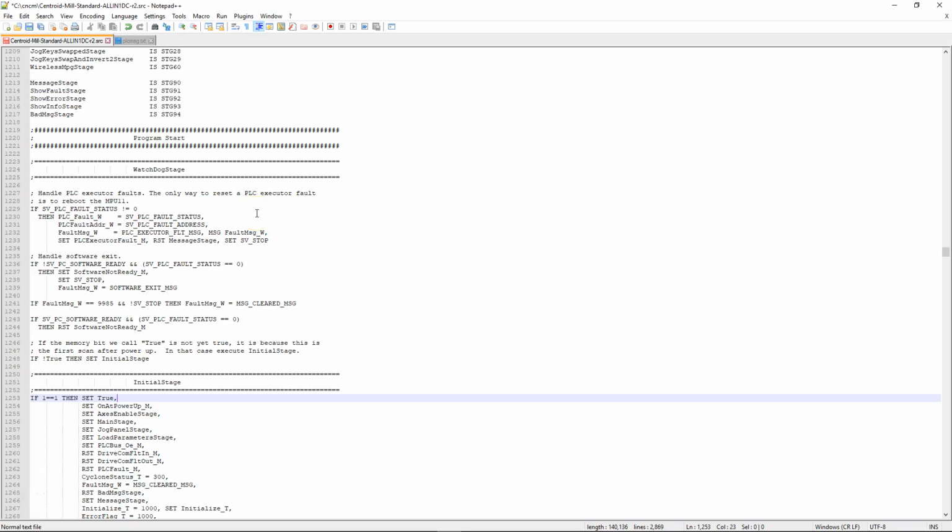All right, now we're actually getting into the logic of the PLC program. The logic is pretty much the simplest form of C, which means that all the logic contains multiple lines of if, some condition, then outcome. Now the outcome can be numerous things. It could be turning an output on and off, turning a memory bit on and off, setting a timer, resetting something, associating a value from one thing to another, performing some math.